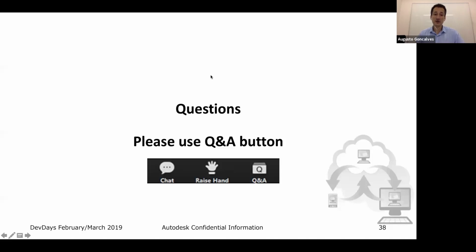That's a very good question and a very important topic. Let's say you want to use Revit in French, for instance. You can just pass FR, and that will launch Revit in French and avoid problems with encoding or types of properties or anything like that. So you have to use the actual engine in the language that we want, not Design Automation, but yes, it's possible.